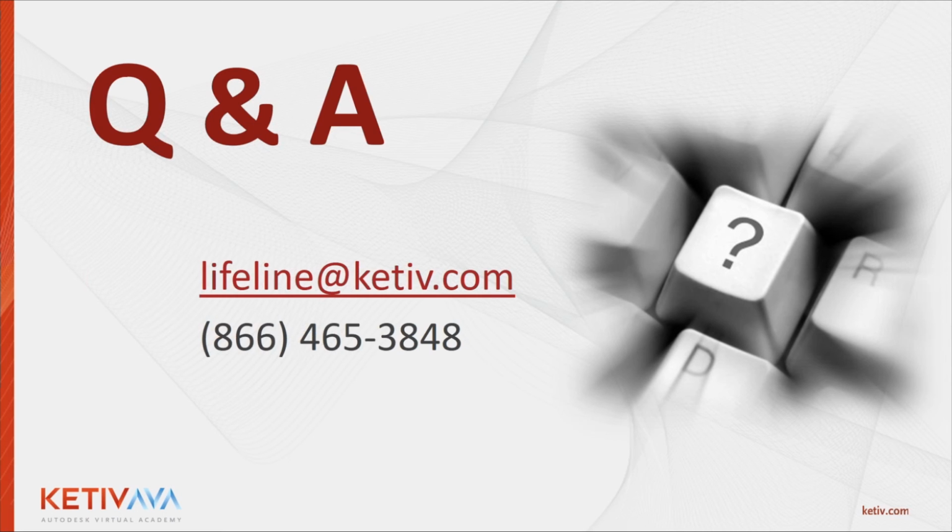The answer is no. No, you can't truly use iLogic with tube and pipe or routed systems very well, or frame generator for that matter. However, once you understand the power that you have with iLogic and its capabilities, you could replace tube and pipe with iLogic rules, and maybe not one single configurator, but a series of smaller configurators depending on what you're trying to accomplish.